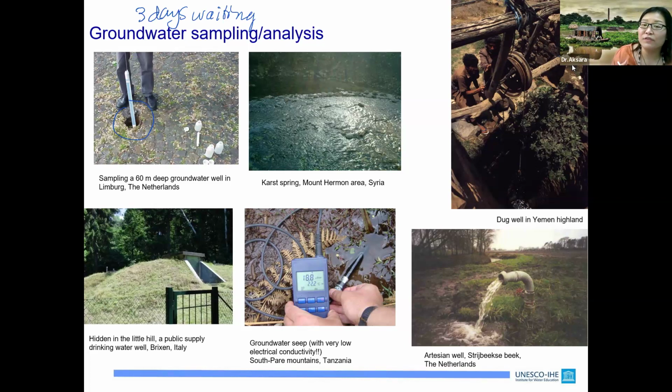It gets lots of soil, dust, rocks and so many things in your water. So your water got disturbed. So what happens after you're done with the well construction is that the groundwater in your well is always very turbid. Okay, the water is turbid.